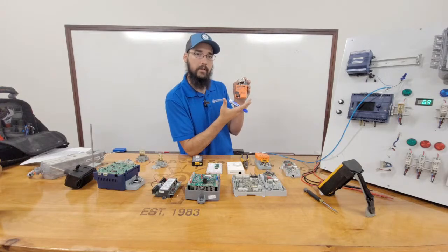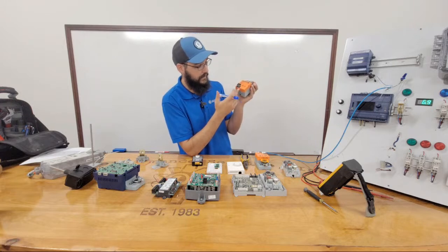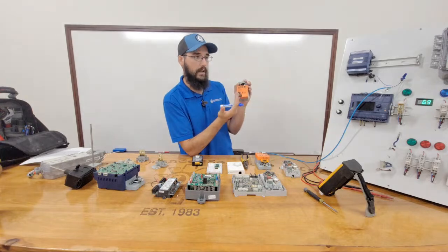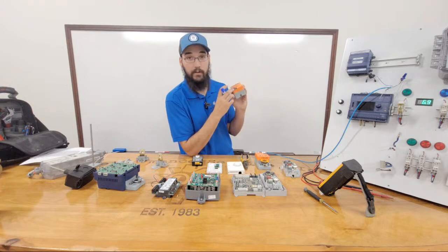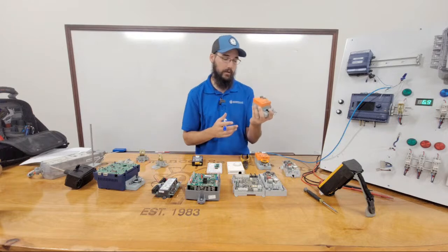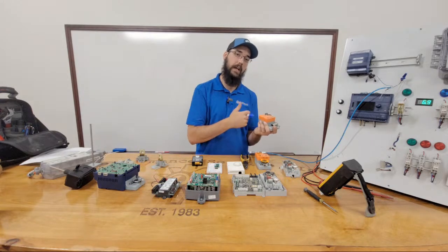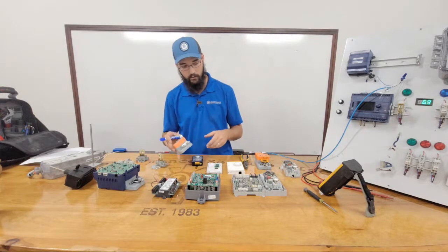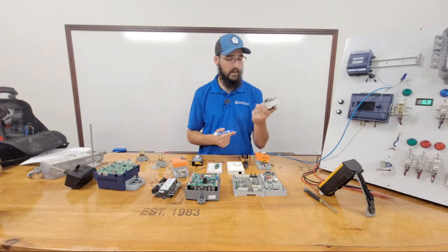And it's just going to wait for me to send another voltage signal back to it. Now, if I did it that way, to rotate it back counterclockwise, I would have had to put voltage on terminals 1 and 2 at that point. So terminal 1 on this particular one is your common terminal, and then 2 would be your counterclockwise, 3 would be your clockwise.